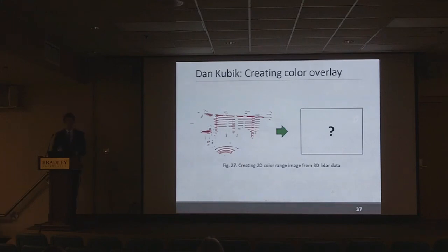I guess 2 big challenges to create this are: one, how do I go from the 3 dimensions of this LiDAR data down to the 2 dimensions of this picture? And two, notice that in the LiDAR data, there are gaps in between the data. That's because of the spacing of those individual lasers. So for our final picture, we don't want those gaps. We want to have hopefully a smooth picture if possible.